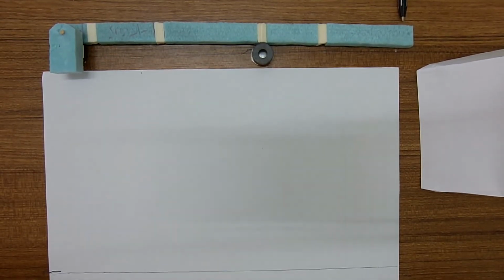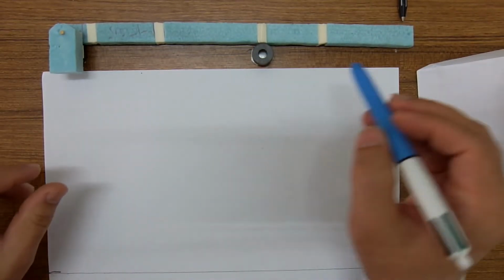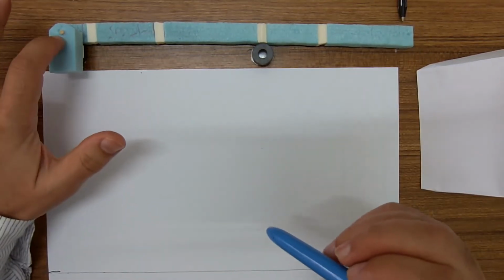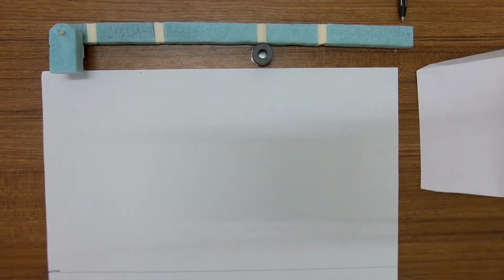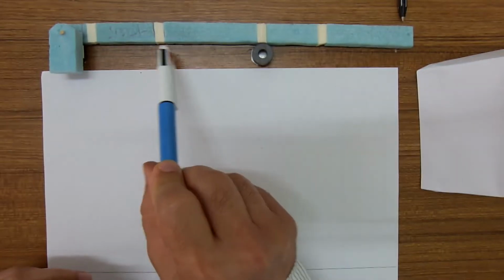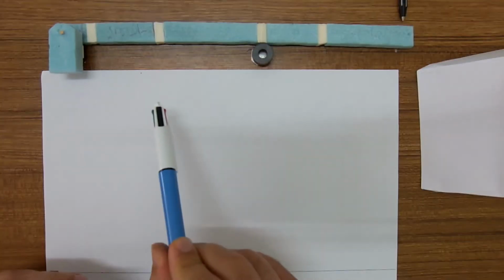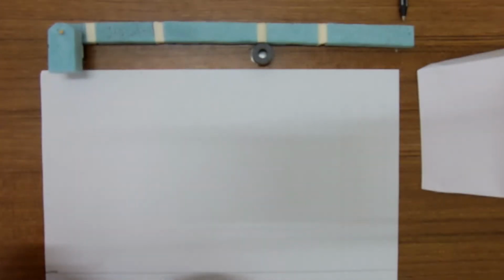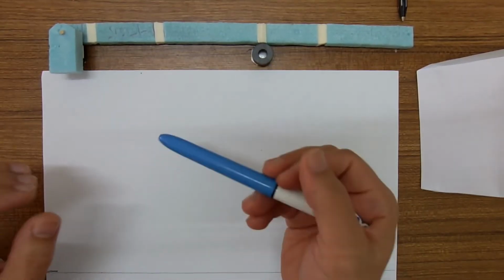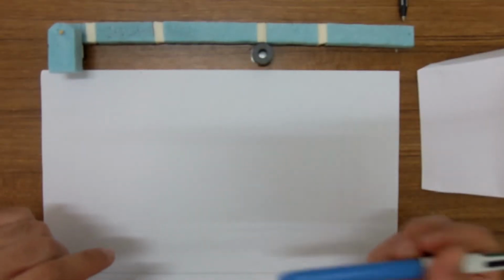Hello everyone, in this lesson we continue our discussion on bending. Here you see a beam point loaded at the right hand side, pin supported at the left hand side, and at the midst it is roller supported. I did 4 cuts on this beam and placed some soft materials within the cuts so that we can visualize the deformation better, and I believe that it would contribute to our understanding of shear moment diagrams.